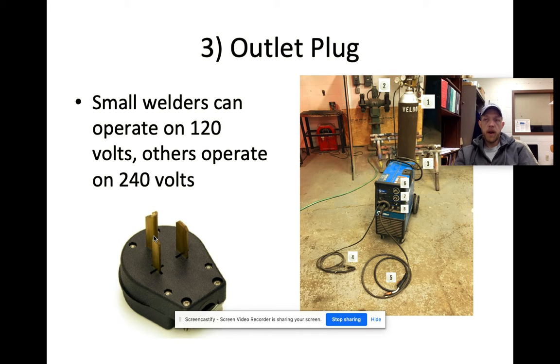If there's a malfunction with the breaker, it could actually cause an overload to the system, and you could see an electrical fire. So just something to be aware of. Most of the time, these welders are going to operate on 240 volts, and they even make some models that can switch between 120 and 240. Again, when we are plugging in any welder, even the BuzzBox Lincoln welders or a MIG welder, we want to make sure we're keeping our contact on the plastic or rubber coating of that plug only. We do not want to ever touch those metal prongs.